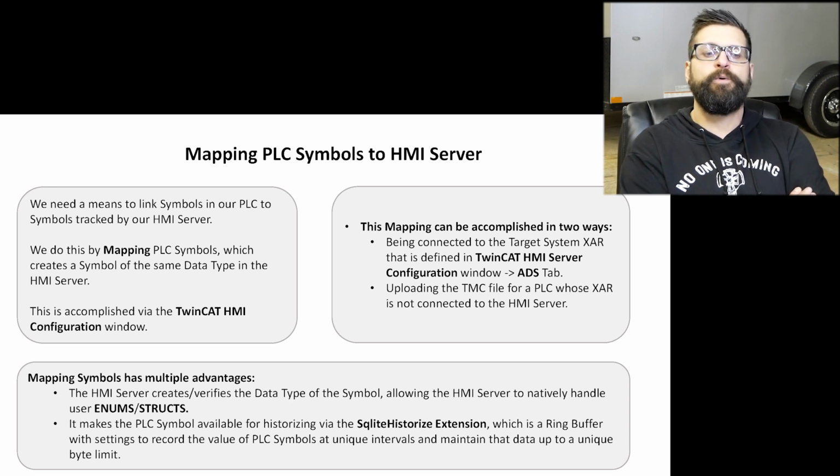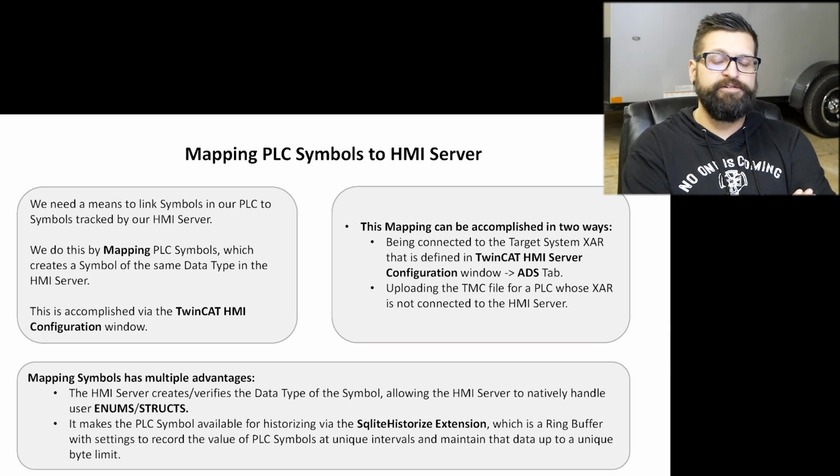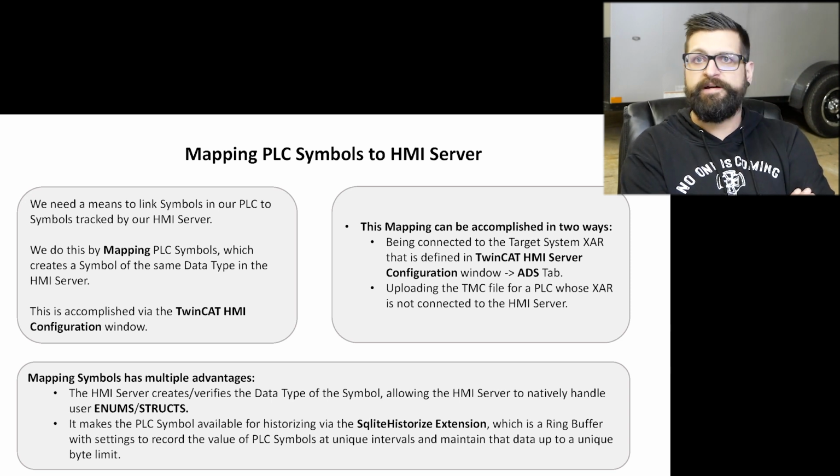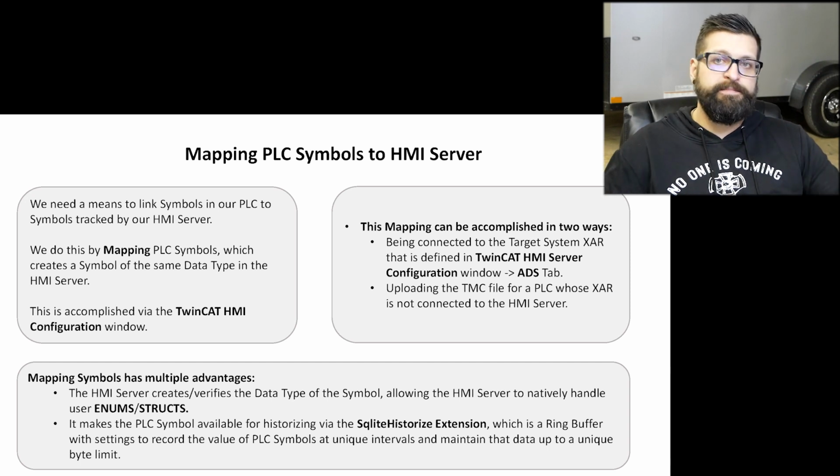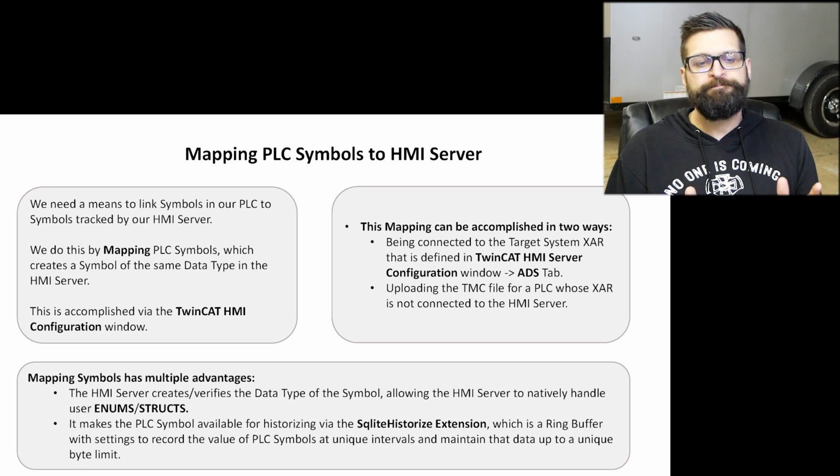You don't have to worry about setting up controls off of each Boolean in a multiple Boolean structure. So it's really nice with respect to that because what we'll see down the road is that kind of architecture, where you're using structures and you have repeatable templates in your PLC code, transfers really well to templating in your HMI, which cuts down on development time. It makes testing much easier. And it makes it much easier for people looking into your code to troubleshoot, because they see the same kind of patterns repeated over and over and over again.